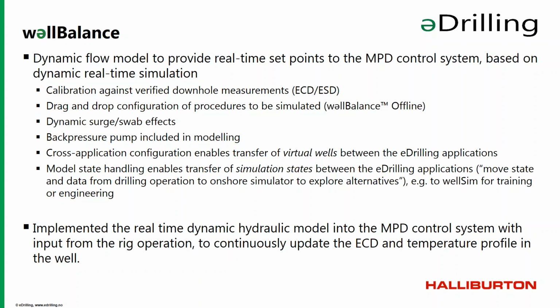If you do the planning in the well planner with the MPD functionality, you can just copy the well configuration directly over to the real-time WellBalance, which makes it quite easy. So you don't need to do the configuration many times in different places. We also have the model state handling that enables the transfer of simulated states.